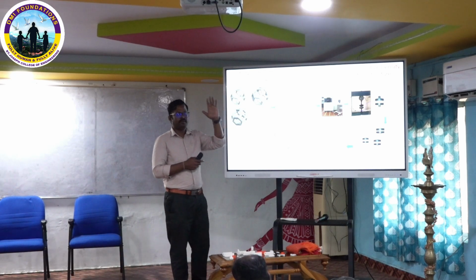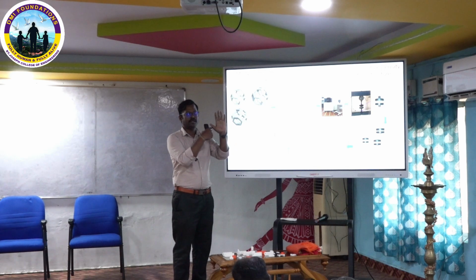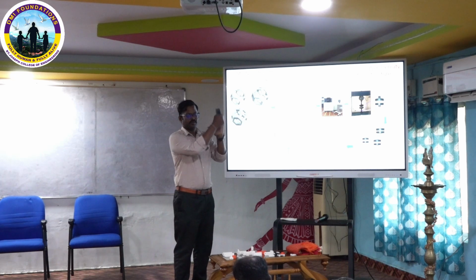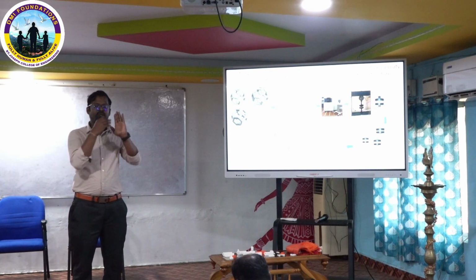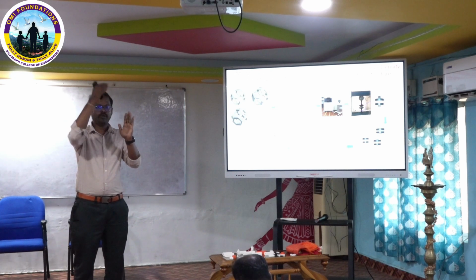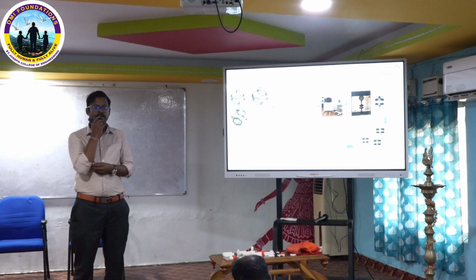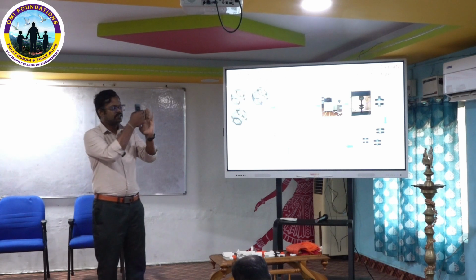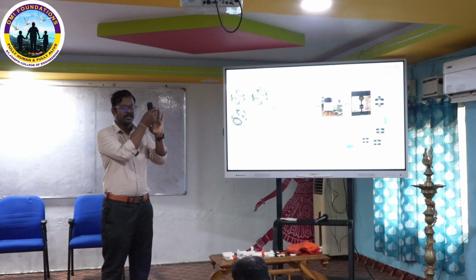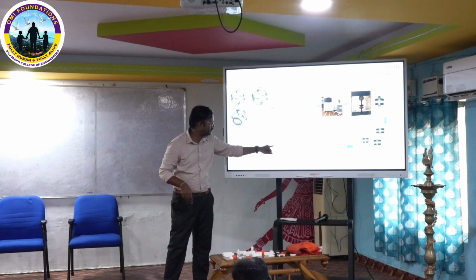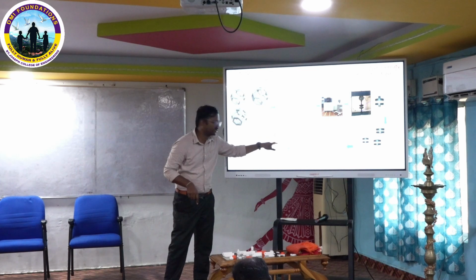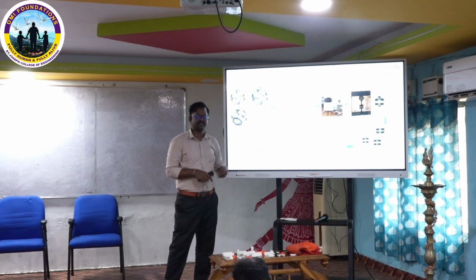Hatching distance is this: in SLS 3D printing, if this is my cross section, my laser will sinter line by line, the previous line and then the next line. It is programmable and can go in different manners. One layer will go in the X direction, the next in Y, or both. The hatching distance is the distance between lines within a particular layer. The first and second lines merge in an overlapping area, and that overlap is 0.2.